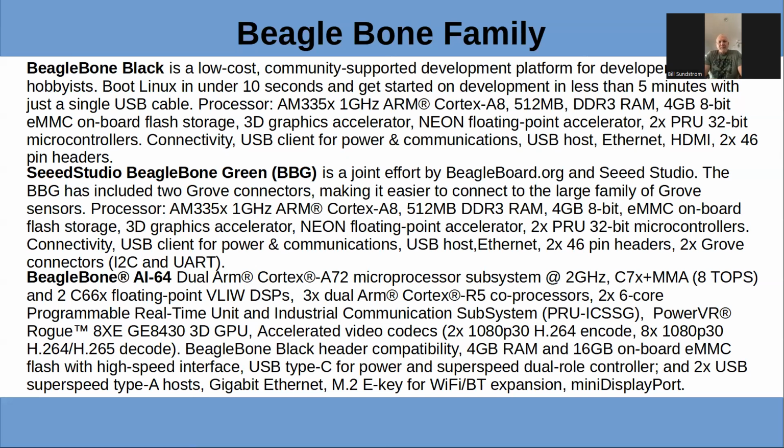It's a kind of standardized set of sensors, smoke sensors, temperature sensors, all kinds of gas and output things, relays, all that kind of stuff. And they all use a common, I think it's a 4-pin interface, what they call a Grove interface. So you can get a board, or in case of the green, it's got some connectors on it, and just plug these sensors in directly and program them.